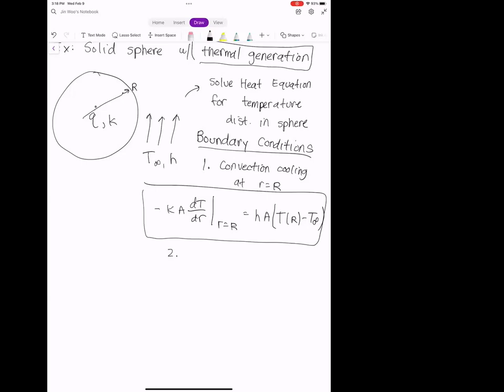The other boundary condition is not obvious, but we did do an example like this on Monday with the solid cylinder. The other boundary condition, if you can call it that, is the fact that our temperature solution has to be valid at little r equal to 0.